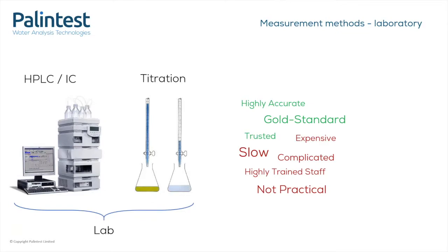Analyses performed in this way are often slow, and the cost of equipment and suitable staff is high. With this type of testing, there is no option to test at the sampling site, which for highly reactive and volatile disinfectants will inevitably lead to negative bias on testing results.